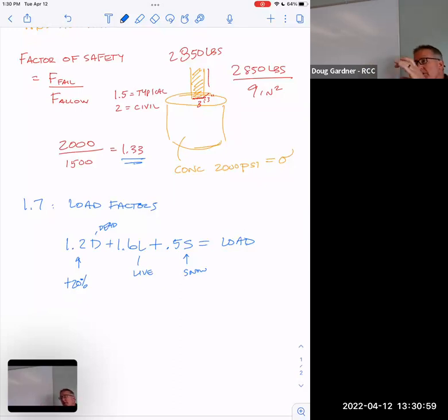But on top of that, we used to put a flat washer that was about 1 inch in diameter. So you drill a 1/2 inch hole for the bolt to go through, and you put a 1 inch washer on the top of it. Well, they decided that's not going to work because the wood could lift up and fold that washer and it could come up. My thought was the house weighs 50,000 pounds. It's not going to lift up in the air when you have bolts everywhere. So they changed it, and now it's got to be a 3 inch by 3 inch steel square plate.